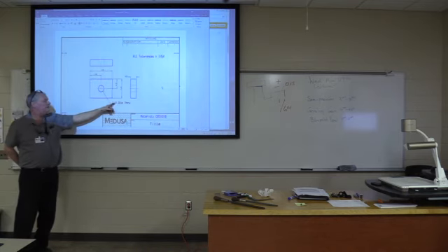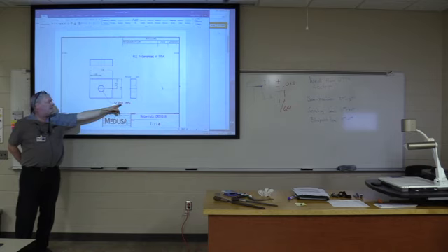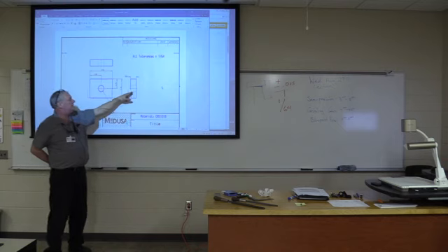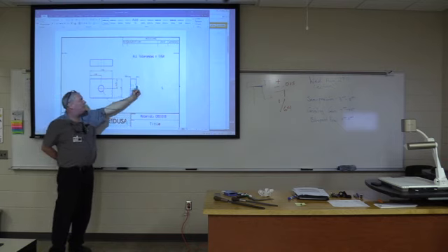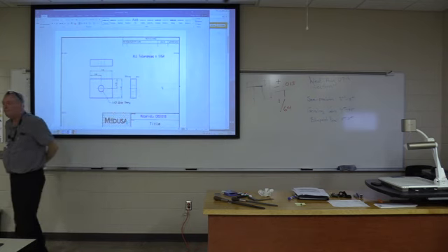That's what this means. 1/2 means 1/2 inch, DIA, I know it's hard to see from back there, but diameter, and it's a through hole. So that's what these little lines show. They show the extent of the hole, and it goes through the entire thickness of the part.